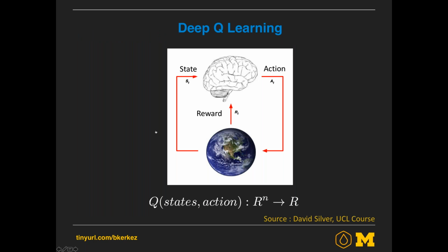So the computer, this agent right here, which I represented as a brain, but imagine this is a computer making decisions, is going to interact with its physical environment. In our case, it's going to be the stormwater infrastructure. And it's going to try out a bunch of different things. It's going to open a valve, close a valve, open a valve, close a valve. And after a while, it's going to determine what the best control strategy is based on the objective that you stipulated in there.